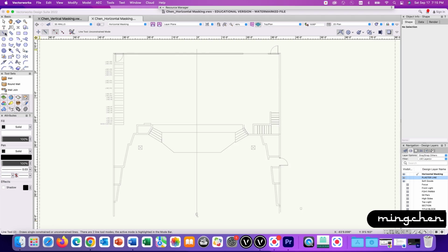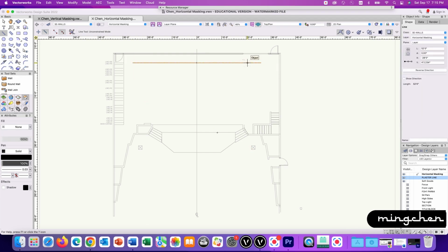Select the Line tool in Basic Palette and click on the Center mode located on the mode bar. From the center line of the theater, draw a 52 feet line that aligns with the last baton position. This is the cyc that blocks the audience view of the backstage wall.